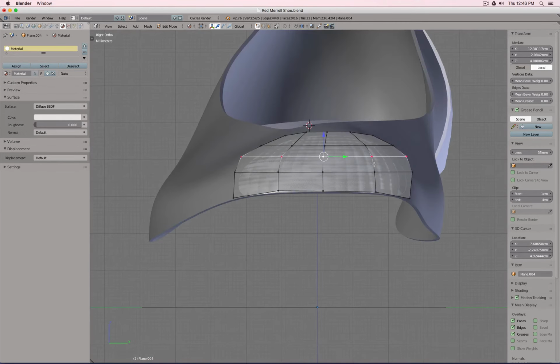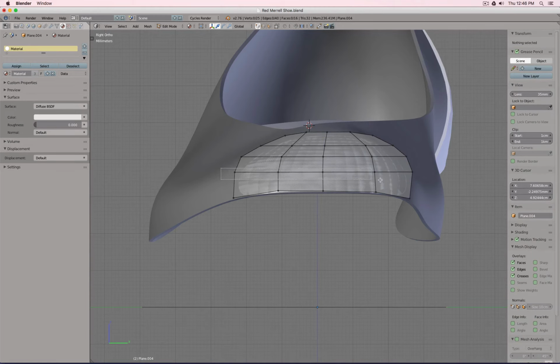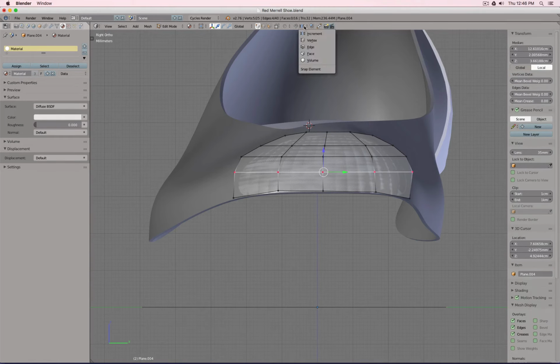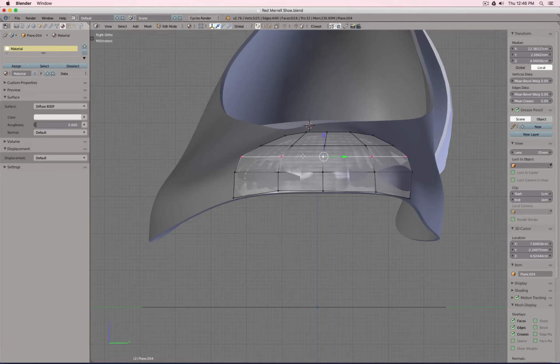So I can, as you see, use the shrink wrap. I can also do something different. I can select all this, then I go to snap to face, multiple points at once, and then currently it's G, so I press the x-axis, I press G and Control, and they snap to it.